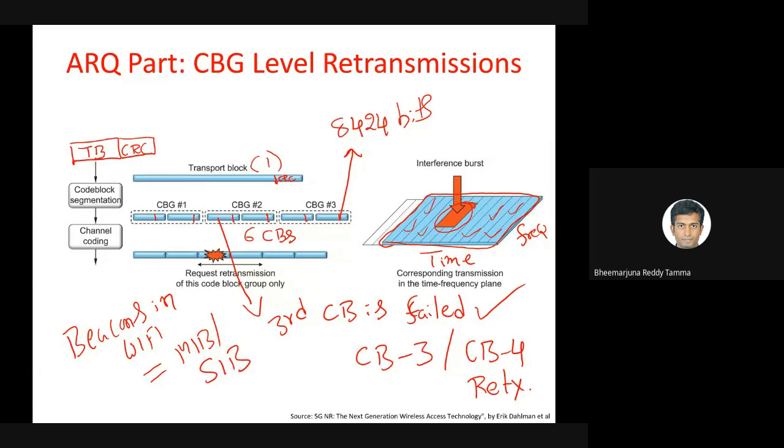They are there all the way from 2G systems. Even in GSM, we use something called training bits. Whenever you are in a voice call on 2G networks, not only do you send the voice bits of the user, you also send certain training bits, which are some predetermined bit pattern that is known between the base station and user equipment. The idea behind sending the training bits is exactly similar to the reference signal that I talked about, where the receiver already knows that from certain location to certain location it is expecting the training bits, and it also knows what the training bit pattern is at the base station.